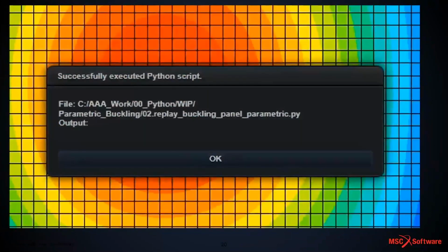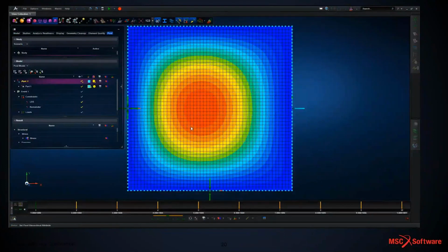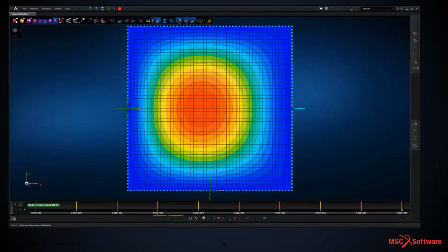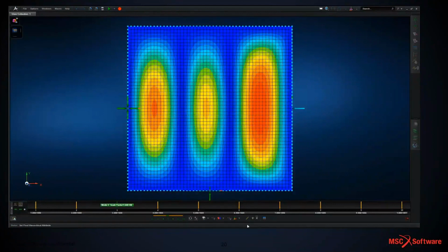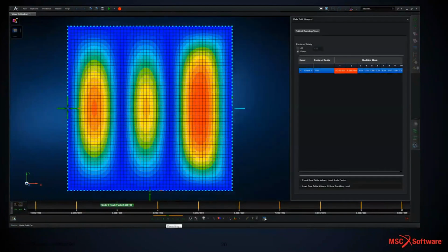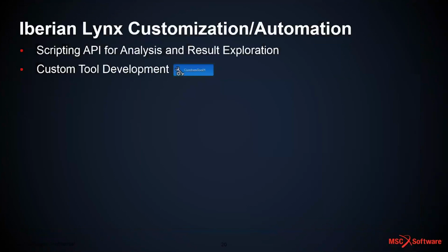And that basically runs through the build, solve, and output. In this case, we're looking at a buckling response for a simple panel. So almost negating the need for hand calc if you wanted to do something slightly more exotic. And we can look in the post-process output for this buckled panel, look at the different modes, and then see that we could potentially have a design problem in that we have a couple of modes where the buckling factor is greater than 1, shown in red in that region.